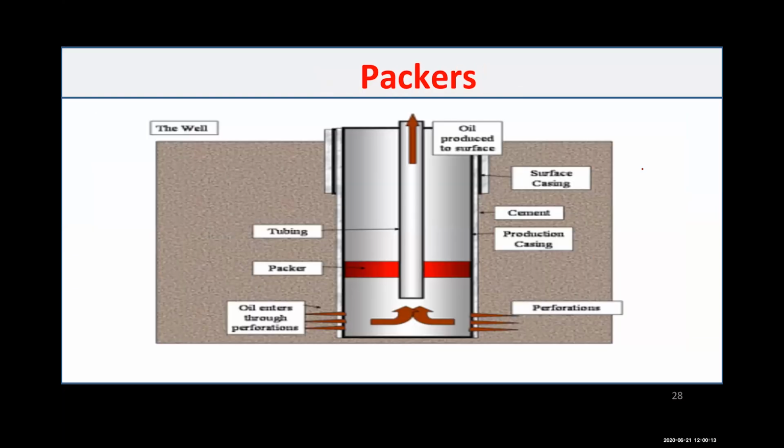A second one is the packer. In this case, you set the packer in the zone that you would like to treat and treat it, then release the packer and go to another section and treat it, and keep going section by section for the treatment.